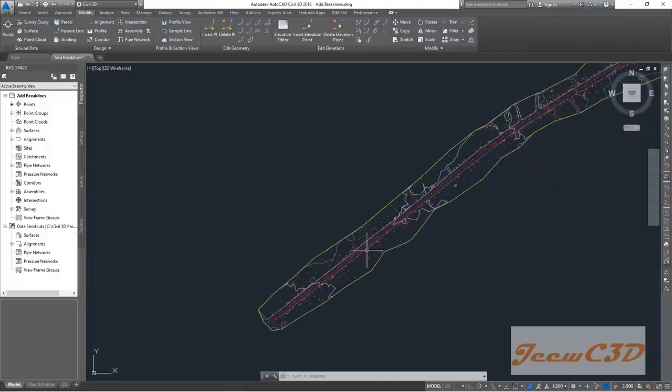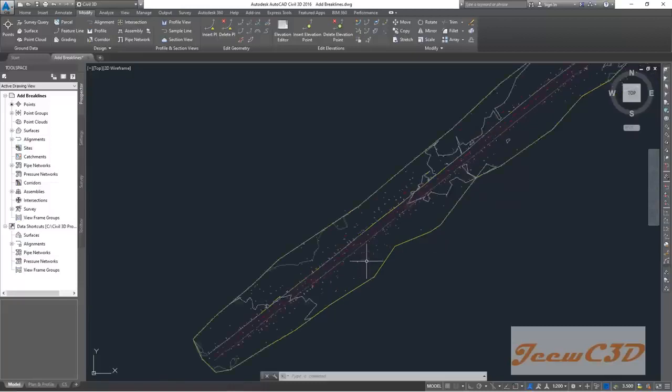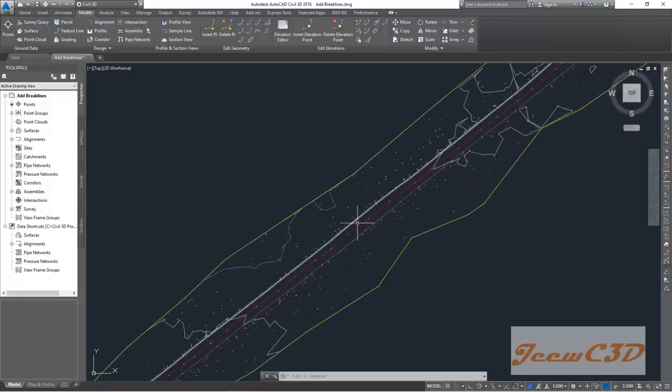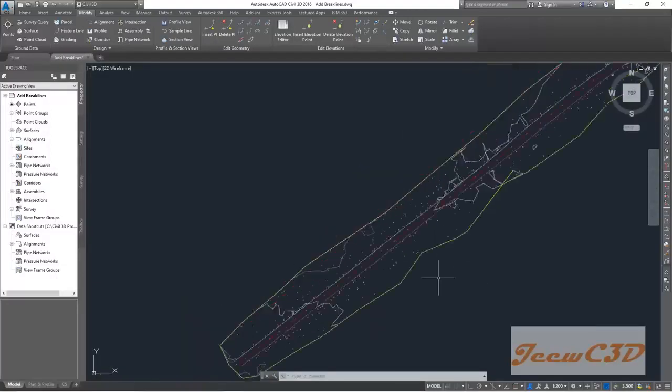So the drawing file which contains the surface would be transferred to a file type called Land XML, where other Civil 3D users can use the surface without seeing these point details, break lines and boundaries, all those things. In the Land XML version, what you have is the final surface only. It will not have the point data and all that.